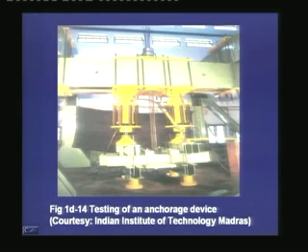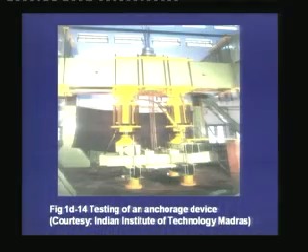Now, this type of test can be done not only for the strength but also for the fatigue characteristics. In bridge decks, the loads are usually dynamic in nature and it can fluctuate over many cycles. In order to see the performance of the anchorage device for varying loads, these blocks can be subjected to fatigue testing.